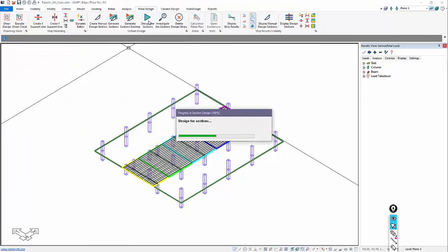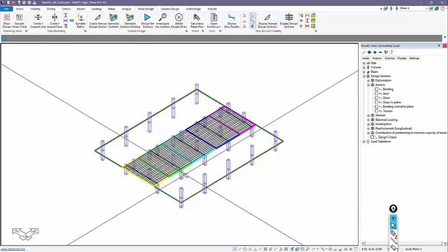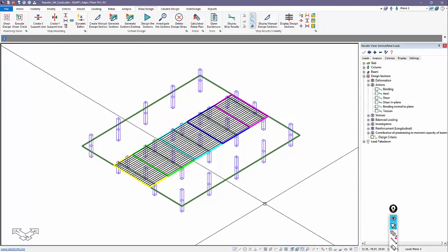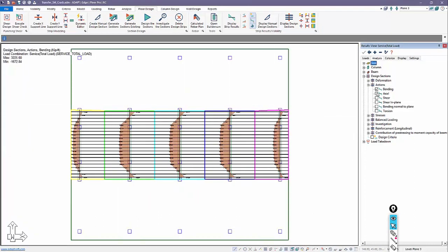This means that the beams are now being designed for uncracked IG equals 1, or 1 times IG, and it's based on a global run, not a single level run. So once I do this, I can again obtain diagrams for bending, shear, axial, whatever the diagram is, and I can again directly go in and generate rebar.